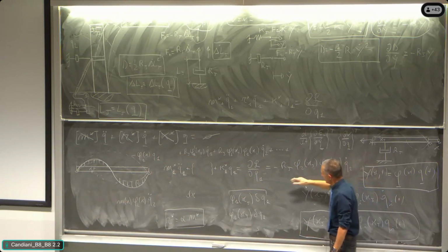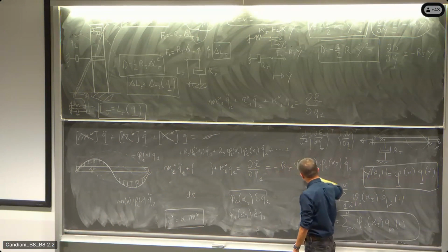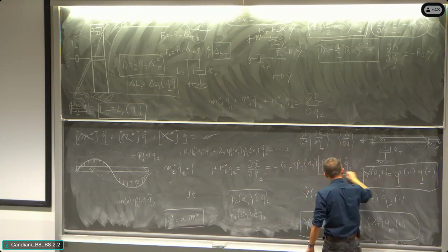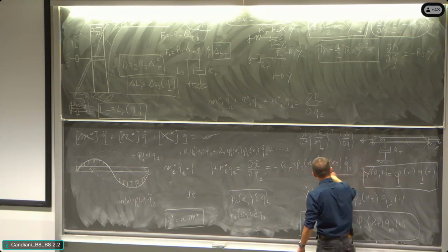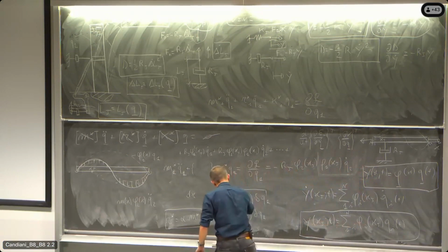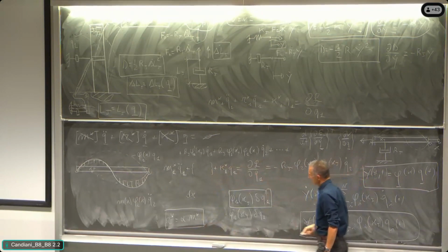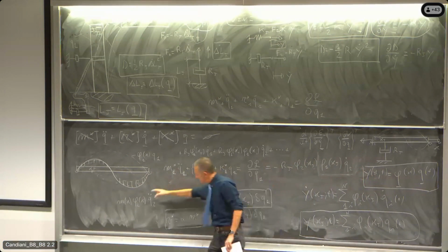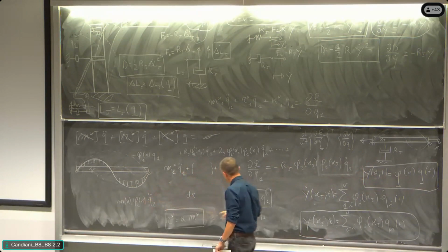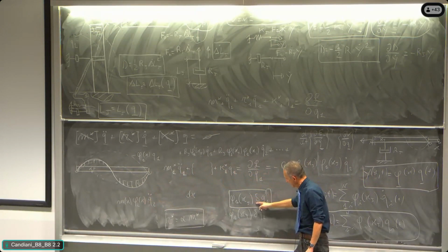So I have to say that I have a virtual displacement of the system that goes with the first coordinate. So the virtual displacement was this quantity here, all right? And so this distribution of inertial force has to work with a distribution of displacement that is the shape of the first mode.